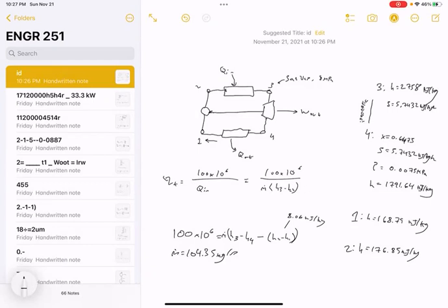So we're getting about 0.3712, or 37% thermal efficiency. That means of the amount of heat that we give to the system, 37% of that is actually being output as work that we can use, right? And of course, this considers the amount of work that goes directly to the pump. We don't get to use that. It doesn't contribute to our net work.